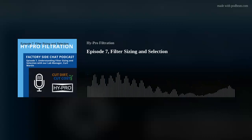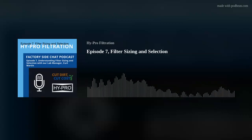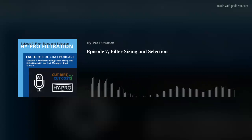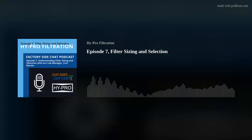Over that, although the DP is fine, the velocity of the fluid going through the element could damage the pleat pack, bend up the pleats, and cause some damage. So that's also something you want to keep an eye on in those high flow situations with low viscosity fluids. Yeah, that's good information.